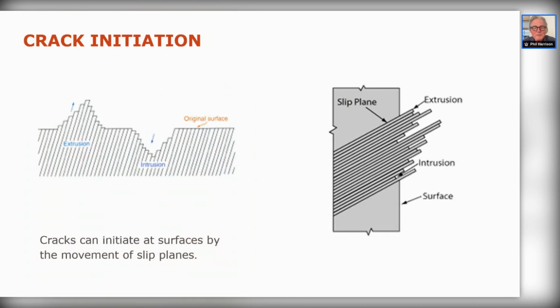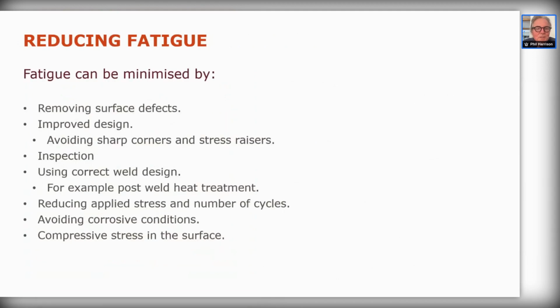Sorry, forgot about this one. I'm going to come to problems. If we could go to the next slide, please, Darren, because I know we're running out of time now. So how do we reduce fatigue? Basically, remove surface defects and improve design, remove sharp corners and stress raisers.